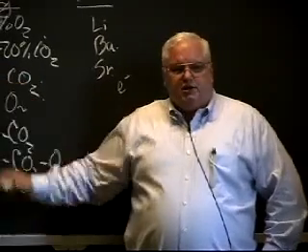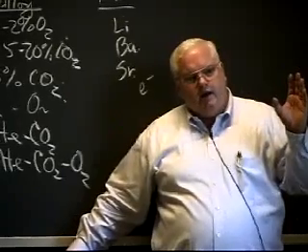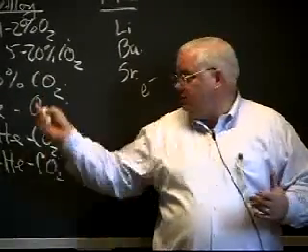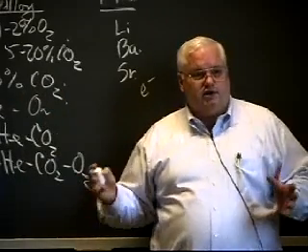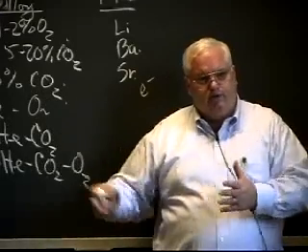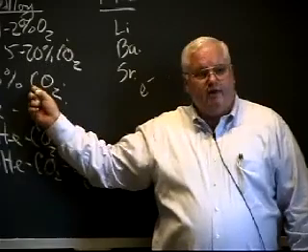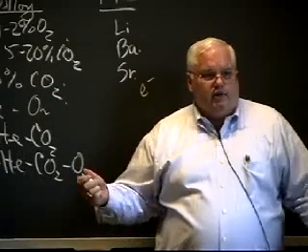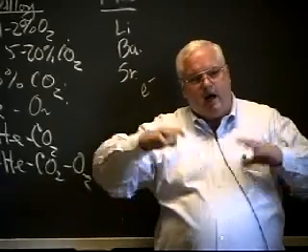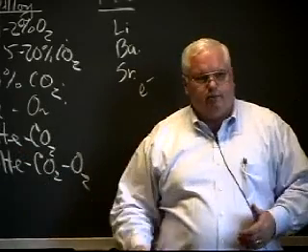The problem with 100% CO2 or with lots of helium is you start getting more spatter. In a 100% CO2 arc, hey, now you're talking a cheap gas. I mean, this is a greenhouse gas. People are trying to get rid of it, and it's all over the world. So you can buy bottles of this stuff for $2 or $3 a cylinder as opposed to $50 a cylinder or whatever it is for argon. So this is a very, very cheap gas. They love to use it in the automotive industry where they're trying to cut costs all the time. The problem is that you get spatter all over the place. Spatter is just molten drops that end up solidifying on your workpiece.